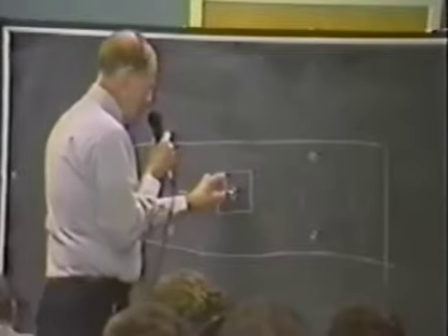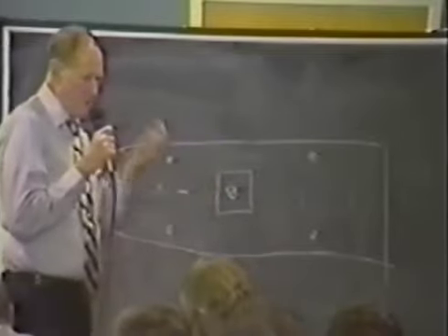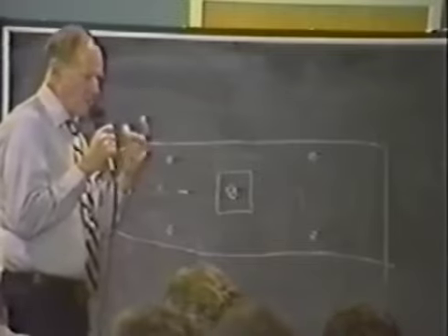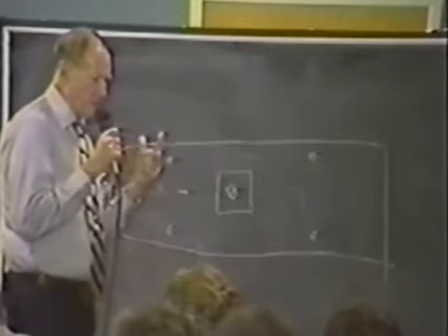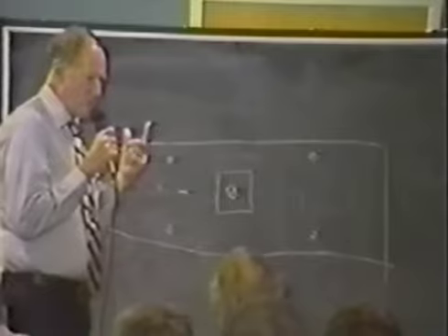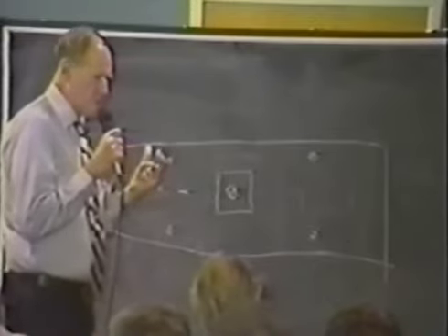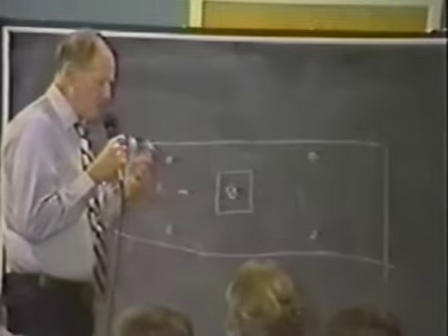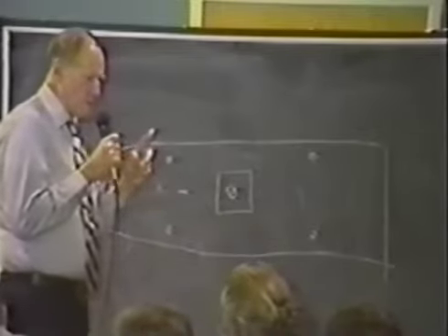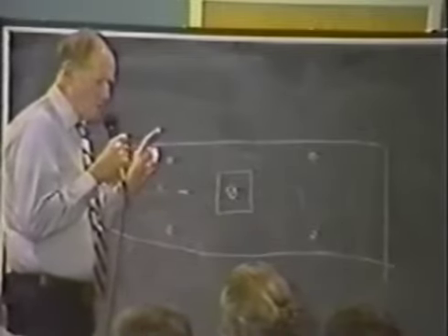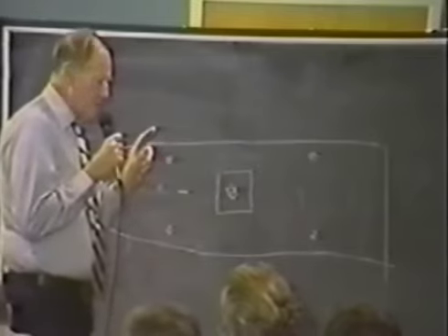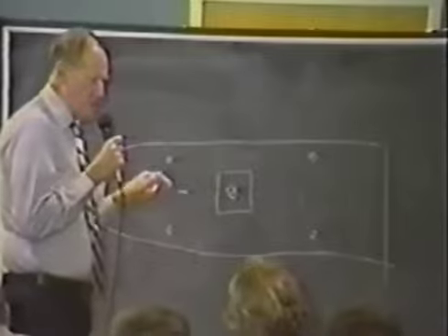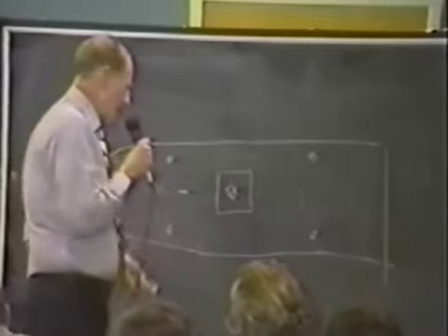The antenna in the center was a quadriphase antenna, which meant it had 4 phased sections to the array, each independently fed by a radio transmitter. Each transmitter was modulated by its own chain of electronics, which went back to the basic pulse generator, the zero-time reference generator, and so forth. That RF system was locked to, in terms of phase and frequency modulation generation to the pulse generator, to the magnetic system, but was independent otherwise.